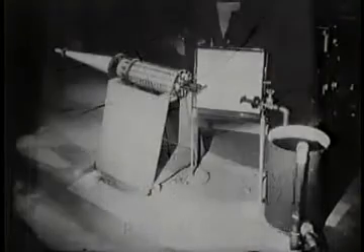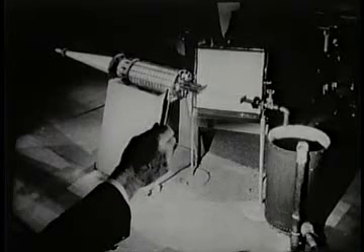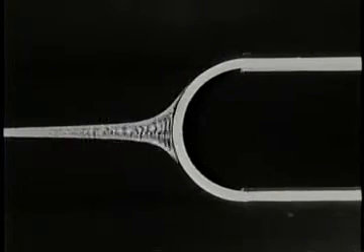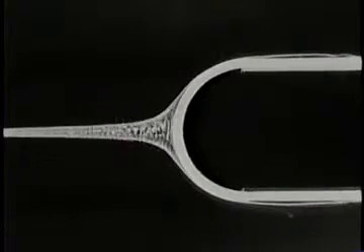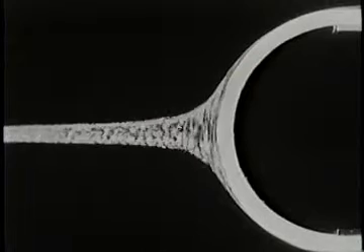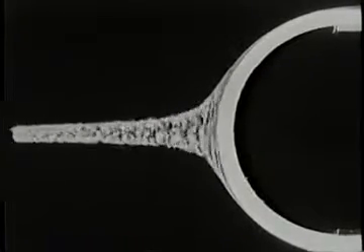A very large reservoir supplying a flow to a duct system is itself a stagnation region. Here is a streaming flow past a blunt body with a central stream tube marked by hydrogen bubbles. The widening of this stream tube tells us that the flow is decelerating. The singular point where the central streamline reaches the nose is a stagnation point. The speed is zero there.